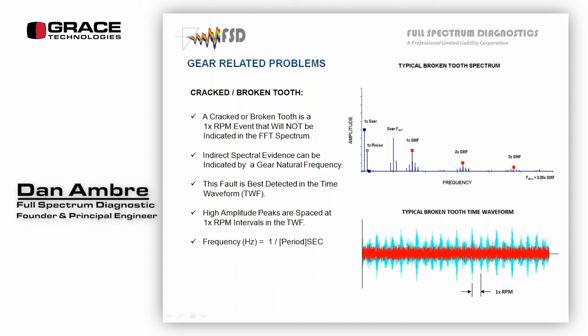And this was an intermediate shaft, and you could see it pulsing, and the pulse rate was at the speed of the intermediate shaft. So we knew right away where it was. Got a strobe light out, and we did a slow roll with the strobe light, and we found what tooth was the problem while it was still running.